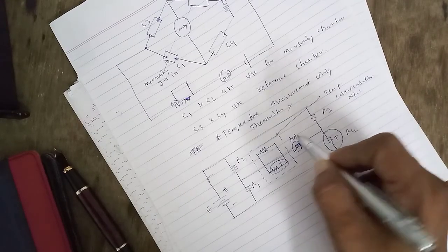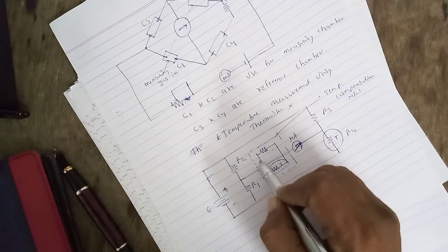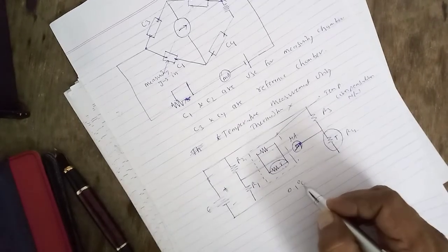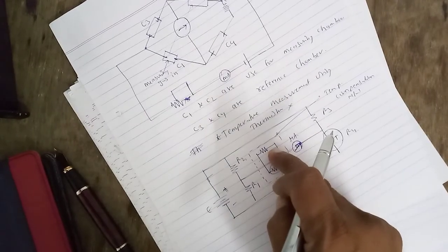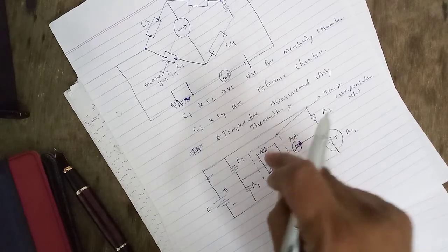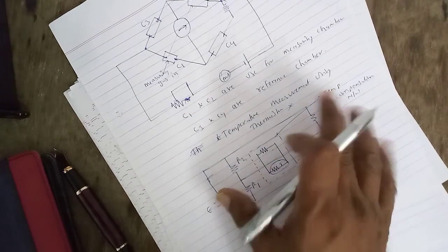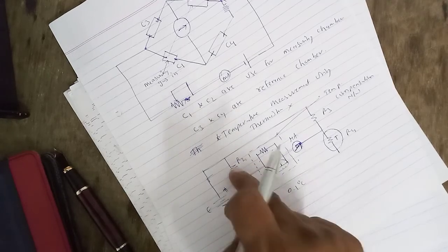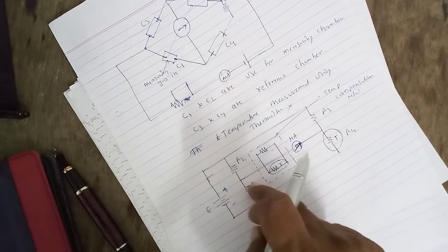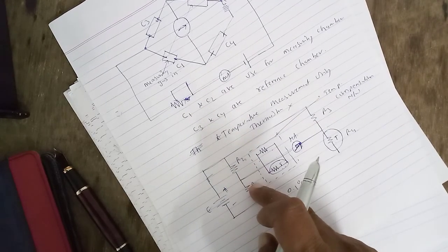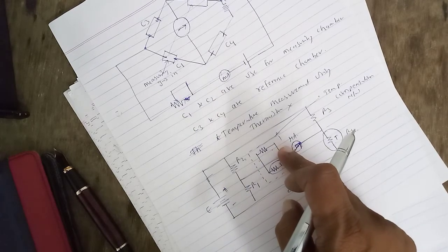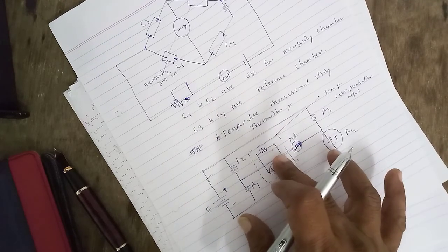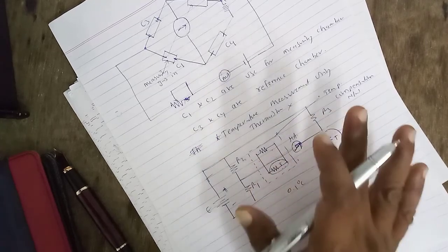The variation caused by the temperature measures a resolution of variations of 0.1 degree centigrade. The higher sensitivity is obtained by the bridge circuit, the temperature compensation network consisting of the thermistors shunted by the resistors. These are the resistors which are shunted. The thermistor with a negative temperature coefficient of resistance is widely used to compensate for the effect of temperature on component and circuit performance.